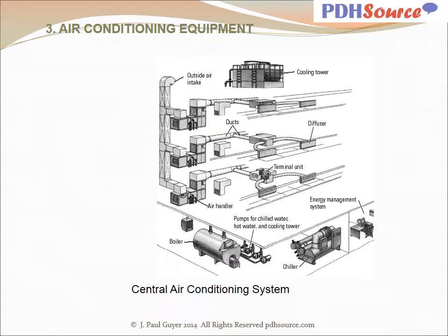And the thing that creates the cold is called a chiller, and that contains all of the elements of the refrigeration cycle. But instead of cooling air directly, it cools water. And so the refrigeration cycle and the refrigerant is all within that piece of equipment called a chiller.